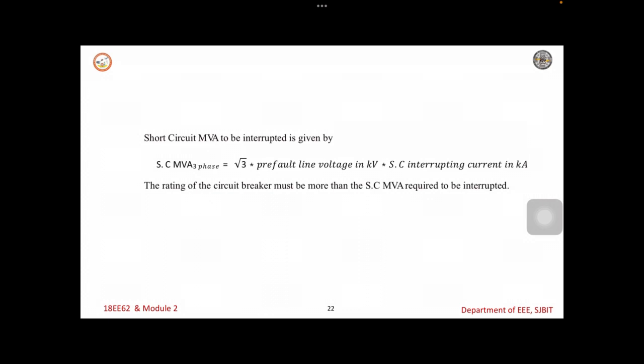The circuit breaker speed is in the first column and the multiplying factor is next. For 8 cycles or slower, the factor is 1. If the speed is 5 cycles, it is 1.1; for 3 cycles, 1.2; and for 2 cycles, 1.4.